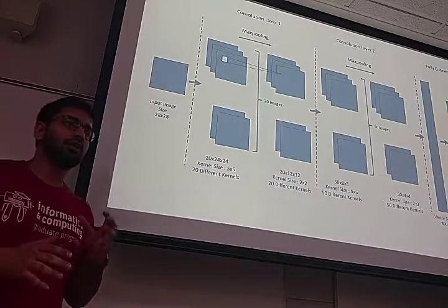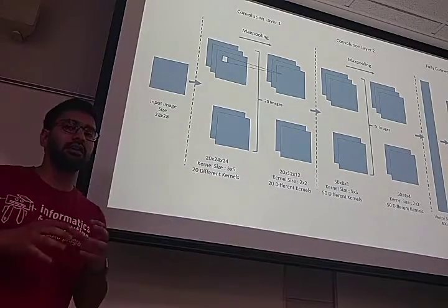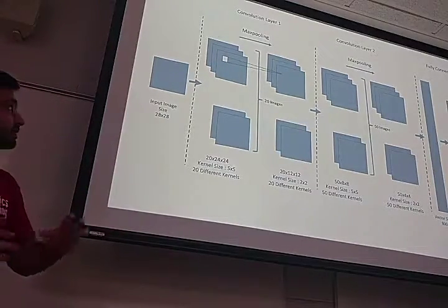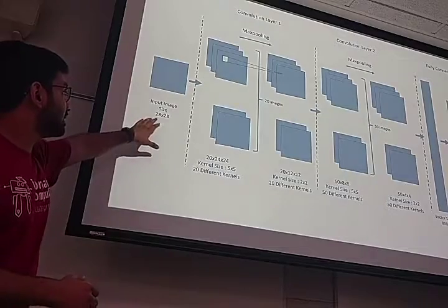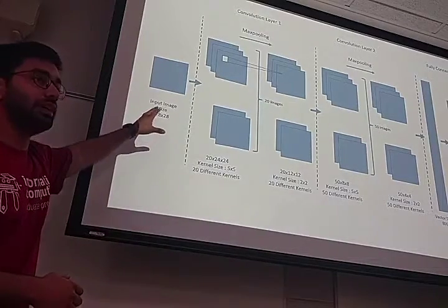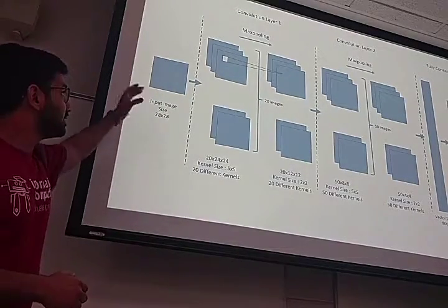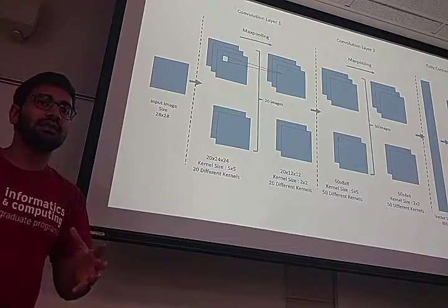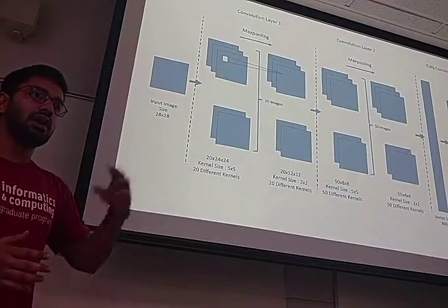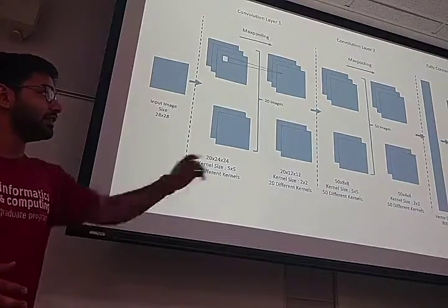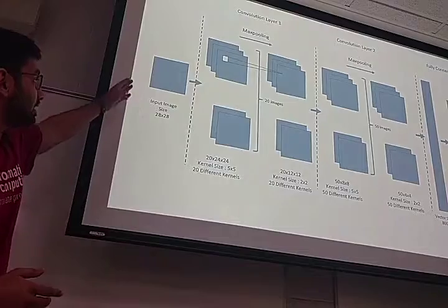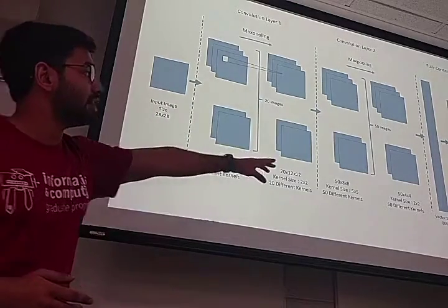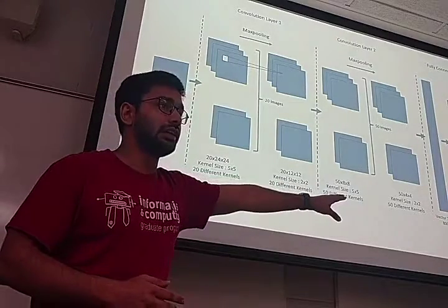Before we start with how we implemented it in hardware, I would like to explain how the big picture works. Consider an image of size 28 by 28 from the MNIST data. This image has to be classified among the 10 classes that we have, according to the numbers 0 to 9. Each input image goes through 2 convolution layers, followed by 3 layers of fully connected network.